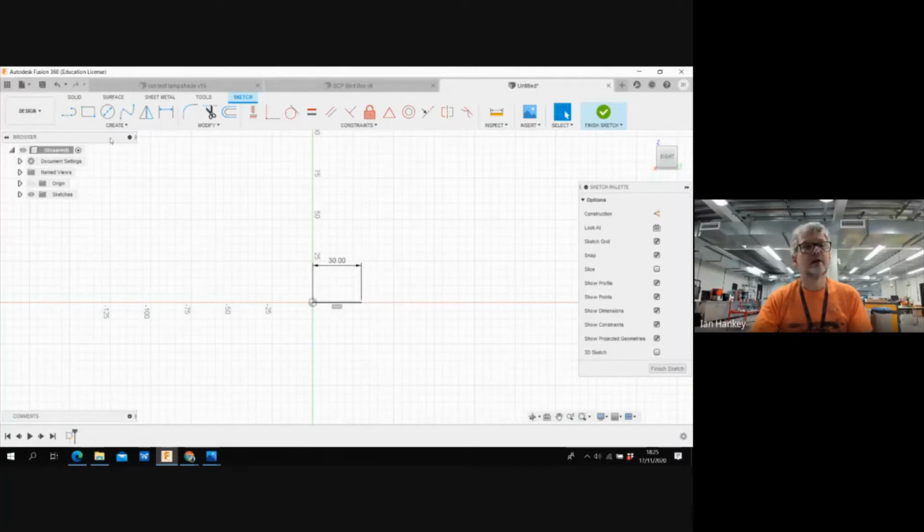So what I'm going to do now is draw another line from the bottom here and go straight up. I'm going to go 75. I'm going to click it there. So there's my second line. I can continue to come out as well, or I can click the little tick there to finish. I'm just going to bring another one out to about 20 and left click again. And I'm going to tick the little arrow there to say I've finished my line so far.